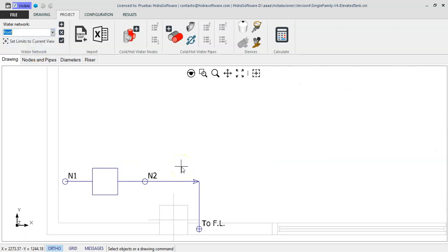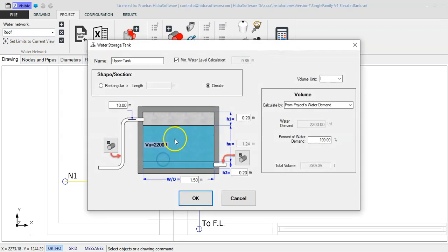For this tank, the average level of water required to guarantee the working pressure of the sanitary fixtures was determined in the automatic design. The corresponding value is approximately 9.9 meters, for which we have chosen the value of 10 meters, here in the scheme, as elevation of the inlet pipe, which, as you will suppose, corresponds to the pumping pipe arriving from the ground level. Thus, we have defined the inflow.